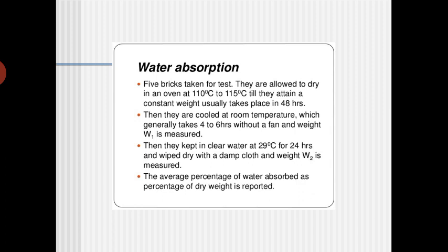What causes this increase in conductivity? It is due to the presence of dissolved solids in the water. So, as far as possible, the dissolved solids should be removed and the conductivity reduced. Then that kind of water should be selected and used for the water absorption test.